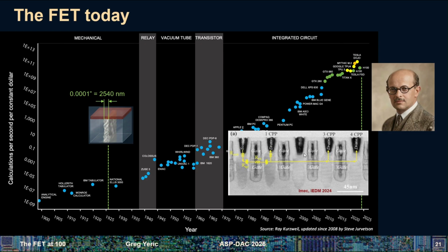again, if this hasn't come up in your class, let's just make sure. The width of a line when you print it will vary day to day, or across parts of the wafer, parts of the die, when you have variations in how long you expose it, or how old the resist is, or the light bulb, in case of lasers in modern day. The actual width of a line will go up and down. Now, the space between lines will go down and up exactly the same amount, right? You're not changing the pitch, which is one edge, like a left edge of the device, to the next left edge of the device. That's the pitch. That never changes, and that's why we often use that word, as opposed to what we really want to look at, which is how big is the gate.